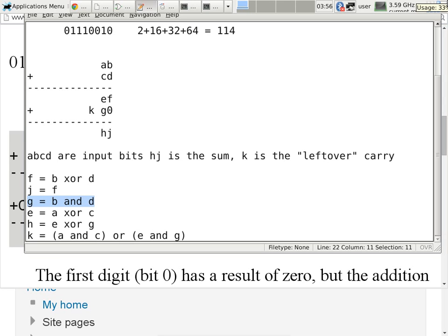Okay, so are there any other questions about how to make a full adder? How to make a half adder, and then out of a half adder, use 2 of those and an OR gate to make a full adder. And using full adders, you can just keep slapping more and more full adders and make your n-bit adder. You just have to do it n times.